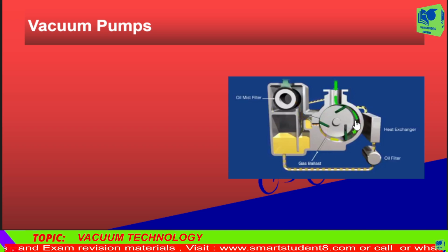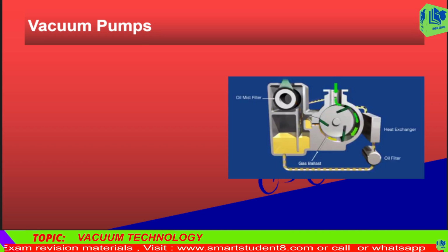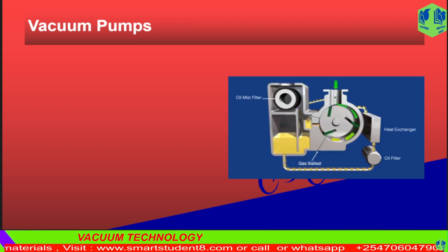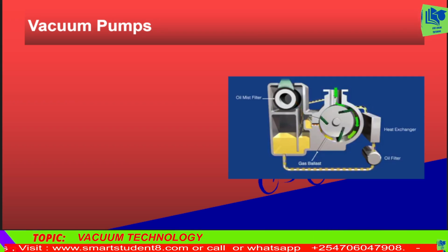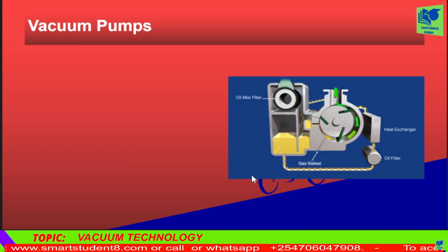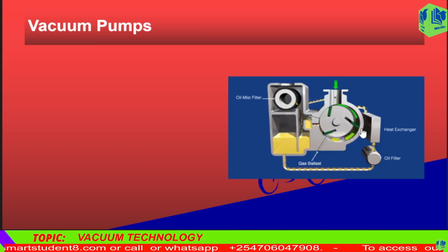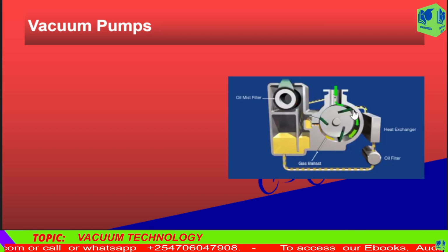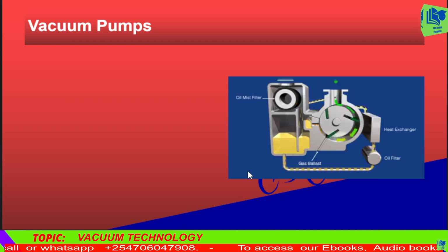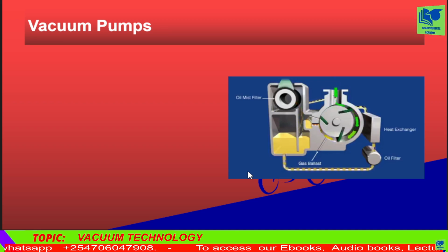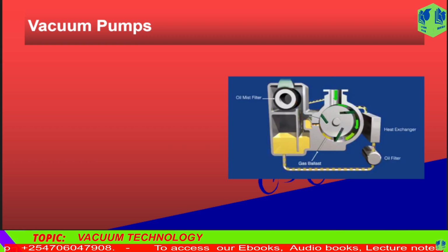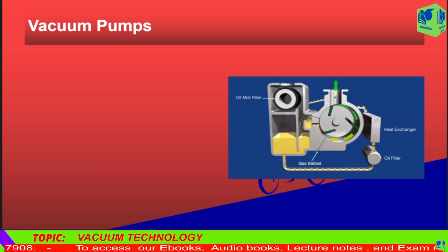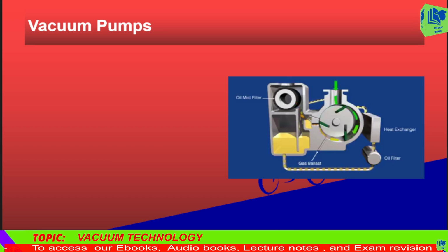How to clean the vacuum system. Chamber cleaning. Depending on the nature of the work you're doing, chambers can accumulate dust, dirt, or chemical residues. Use a soft, lint-free cloth to wipe the inside surfaces of the chamber. If there are stubborn residues, consider using a non-abrasive cleaning agent that is safe for the materials in the chamber. Pipeline cleaning. Regularly check the pipelines for dirt and chemical deposits. For hard-to-reach areas, use a soft brush or cleaning swab. Avoid using harsh chemicals that might damage the pipelines.